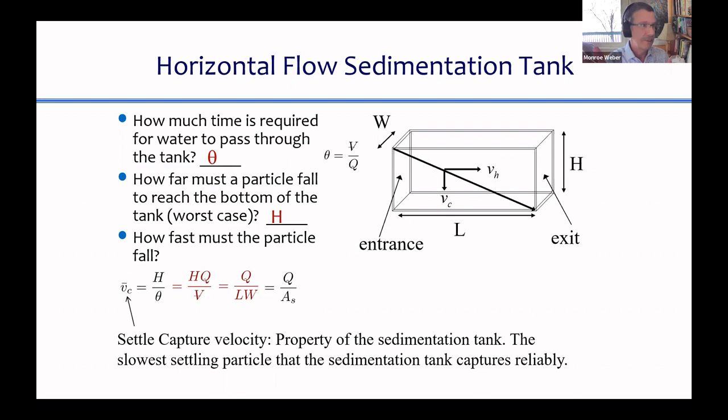So we've demonstrated that this is bad if it gets too shallow. And so we now realize that there are other things that matter besides just the plan view area of a sedimentation tank. But we do have this one cool insight. Plan view area is what matters. And if we build a sedimentation tank like this, it ends up that the plant or the tank ends up being pretty big.